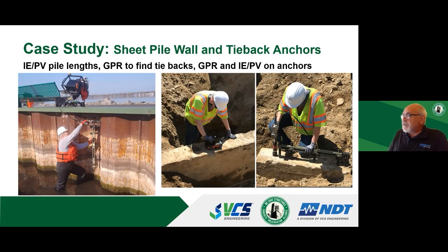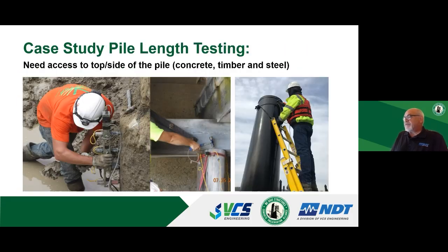I talked about pile lengths. Here's some examples where we're getting the pile lengths of sheet pile. I think there was a dredging operation that was planned. There was no installation depths of the sheet, so we wanted to know how deep they were. And often with sheet pile, there is accompanying tiebacks and anchors, so we could locate them with a GPR and they could excavate up, and then we could quantify what the anchors are for the load rating analysis.